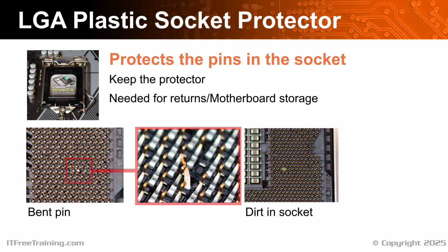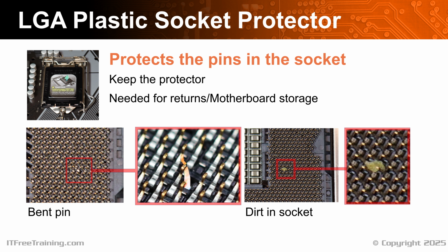You can see in this example, some dust has got into the socket. The dust may not look like a lot, but when I zoom in, you'll see it's enough to cover one of the pins. In the worst case, this will prevent the pin from connecting. The dust may also make the pin connection unreliable, which could result in the computer being unstable and randomly crashing. With such small pins that are easily damaged, you can see why the motherboard has a socket protector to protect them. A single damaged pin can mean the motherboard will need to be replaced.